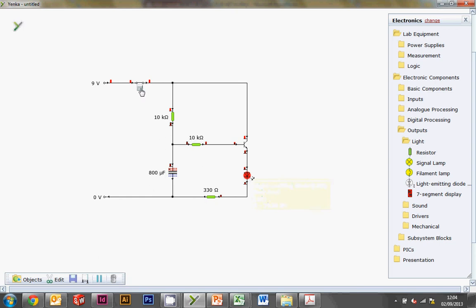And then when we release the SPST switch, it actually goes down very quickly, and we just saw there's a little red dot just left there, and you can see the current still falling. So what happens there is the capacitor is actually still discharging through that LED, and because it's quite a large one, it does take quite a long time to discharge.